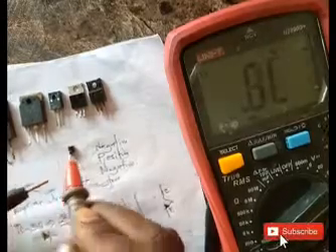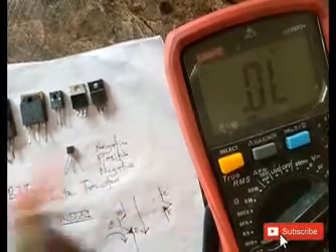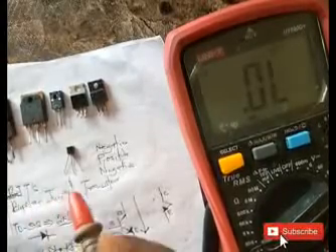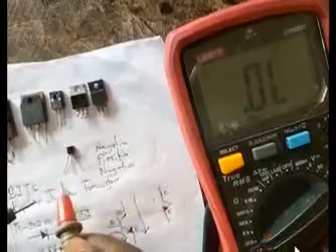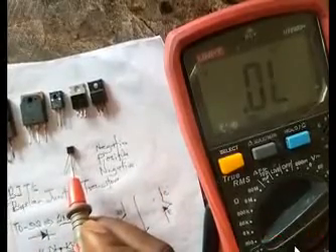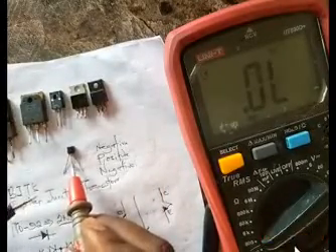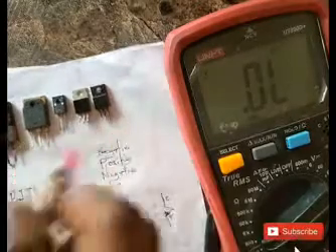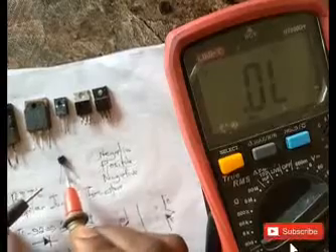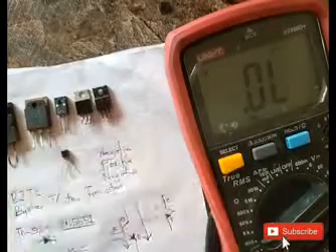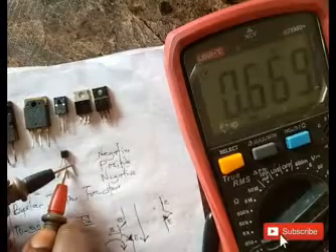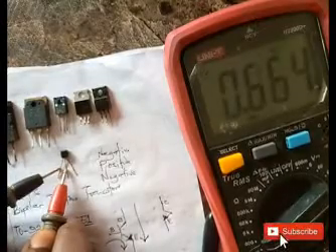All right. Now, this is a key, just in case you don't really know the kind of transistor or the terminals of the transistor. You can use this to know. There's always a higher reading between your base and your emitter. So let's take it again. This is collector, of course, and this is your emitter, 669 and 664. So this transistor obviously is fine.